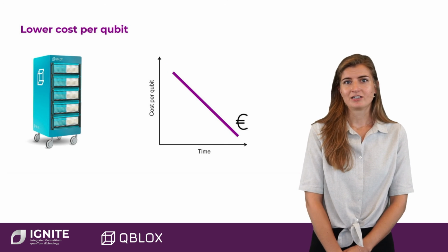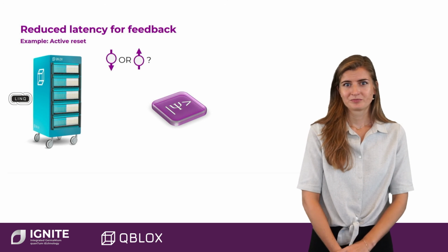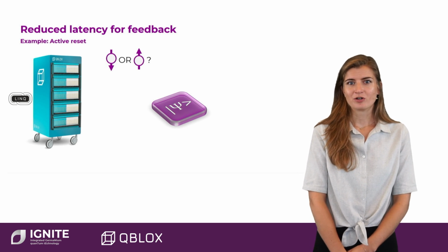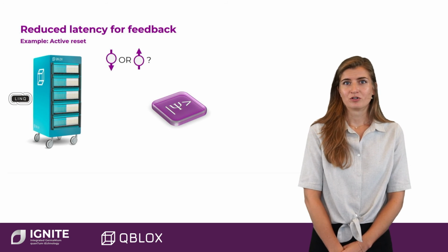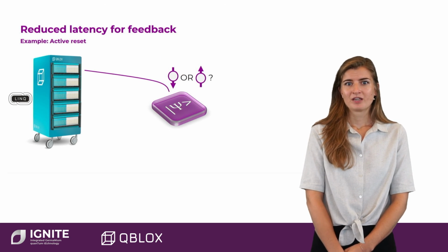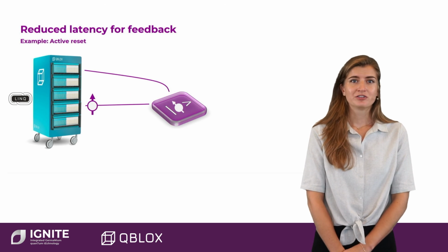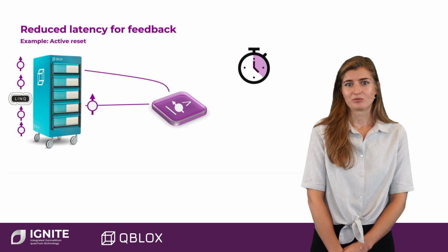With upscaling the channel density, the cost per qubit should go down. Fast feedback protocols should also be extended over these larger systems to fulfill the requirements for full-fledged quantum computers, where active resets, qubit state-dependent gates, and real-time decoders for quantum error correction are all part of the standard protocols.